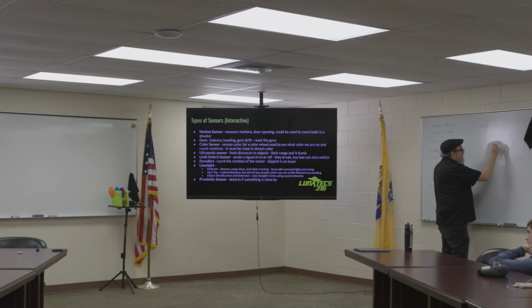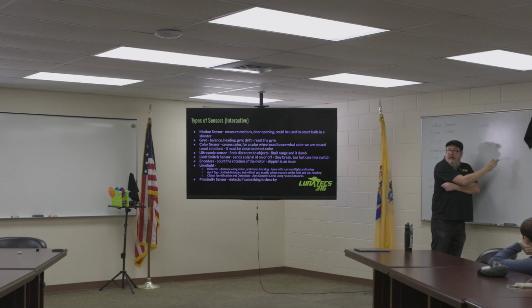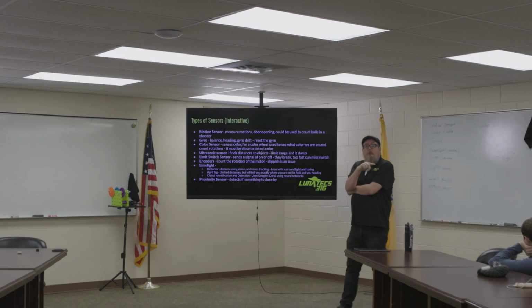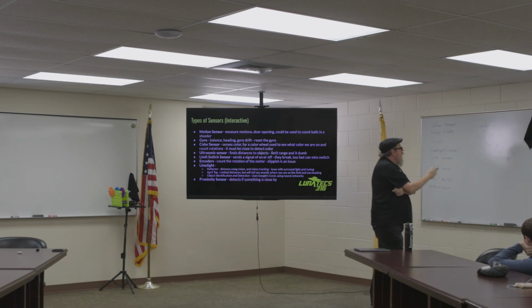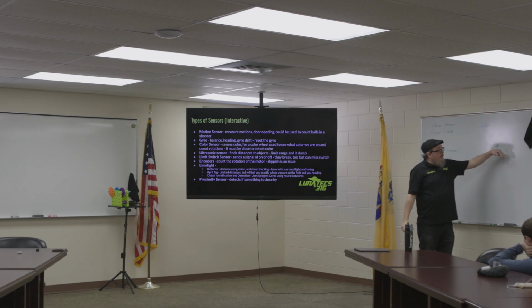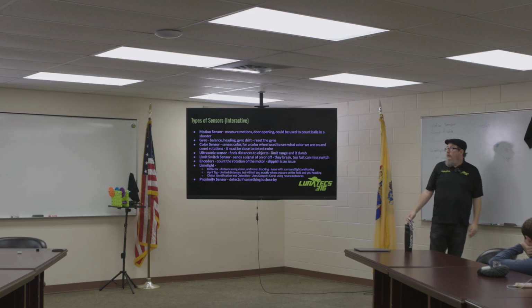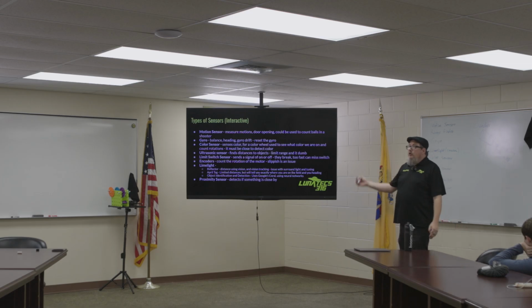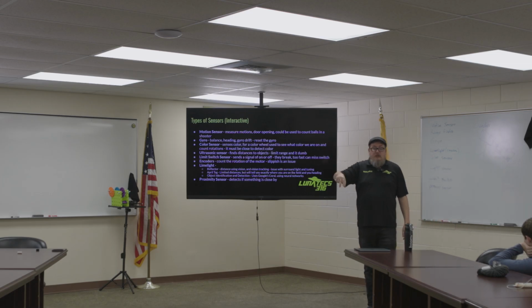Right. So if this is our coral intake, and the coral comes in here, we had a proximity sensor, a rangefinder, at the very end of this. So when it saw the coral, what did we do? What happens if I'm running the motors on here and my motors are pushing the coral in, and I don't stop? What happens to the coral? It'll just shoot out, right? You go up to the human player station, you drop a piece of coral in, and it's just going to shoot right out of the robot.